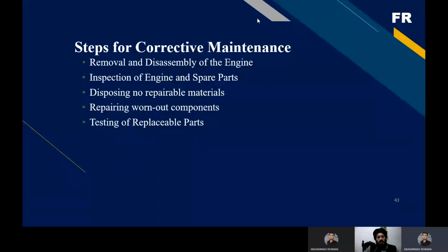Let's take an example. Let's see the engine, our 18V25. First of all, if it is facing a problem in, let's say, the fuel injector, then first of all you have to disassemble that part of the engine and inspect what problem it is facing. And if that problem is repairable, then you can repair it.